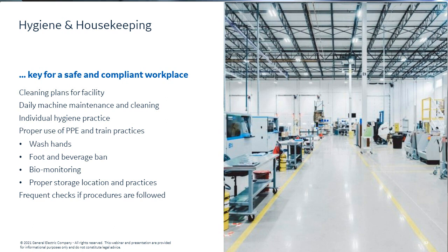Also, consider the individual health hygiene practices. That means the proper use of PPE, and also train people how to do that. Tell people that they should wash their hands. Don't have food or beverages in your additive manufacturing environment. It would not be a very nice scenario if people really ingest all these powders. That can maybe also trigger some biomonitoring requirements in some jurisdictions.